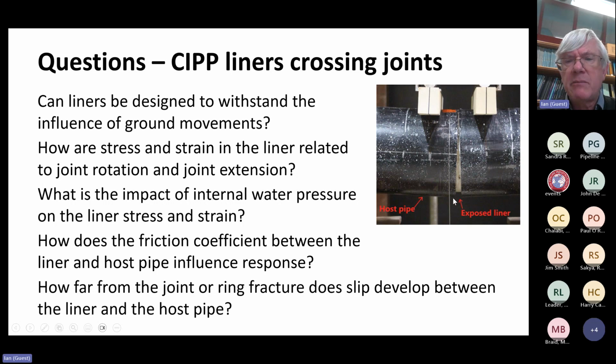Very good. So where that crack or that joint is opening at the bottom here, as a rotation is imposed across this joint or this fracture, we will get stretching of the liner at this location. And so some of the questions that we've been working to address is, can liners be designed to withstand those ground motions?